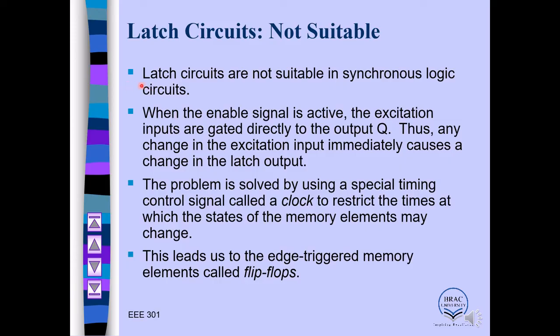So our latch circuits are not suitable in synchronous logic circuits. That means if the logic circuit is synchronous, in that case our latch is not suitable. So we need to do some kind of arrangement so that we can use a latch or a similar kind of flip-flop in a synchronous logic circuit.